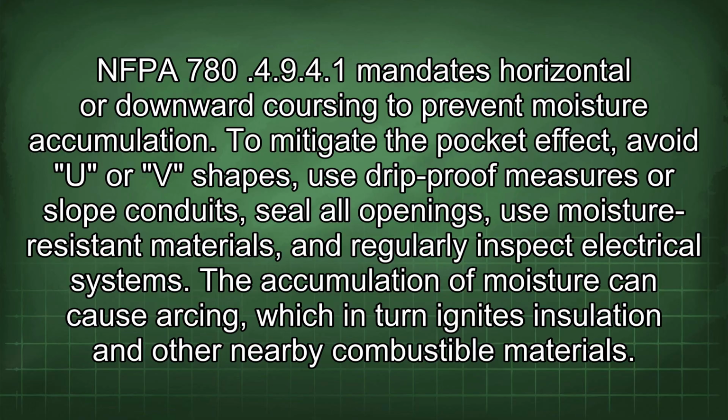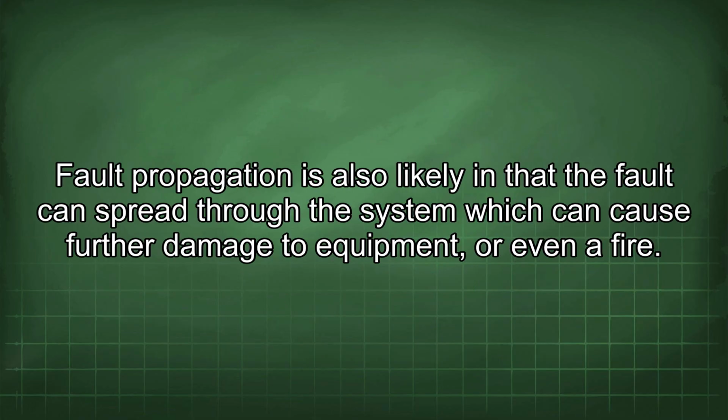The accumulation of moisture can cause arcing, which in turn ignites insulation and other nearby combustible materials. Fault propagation is also likely in that the fault can spread through the system, which can cause further damage to equipment, or even a fire.